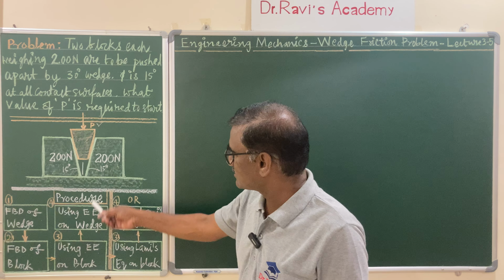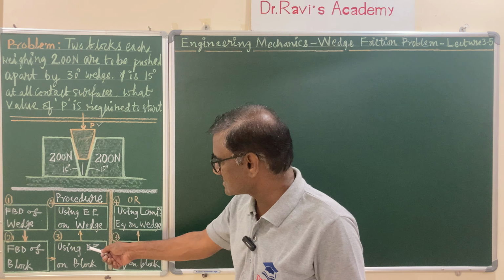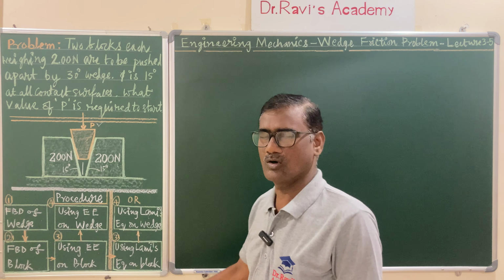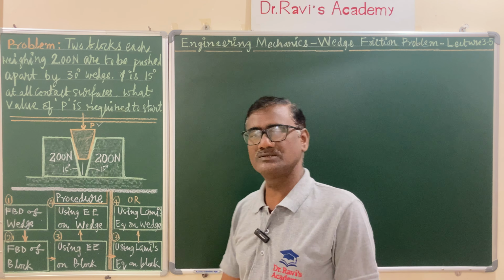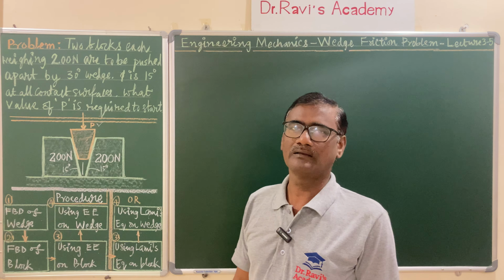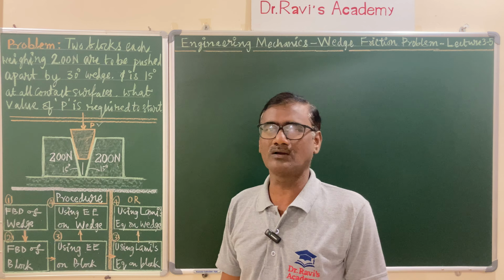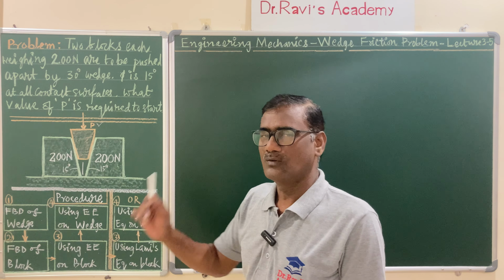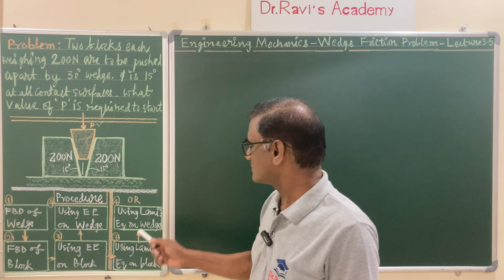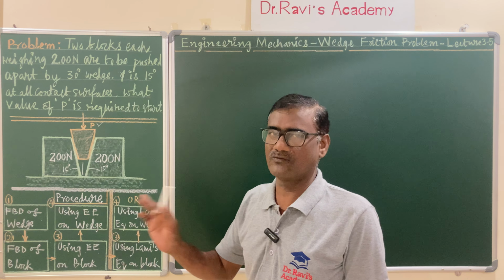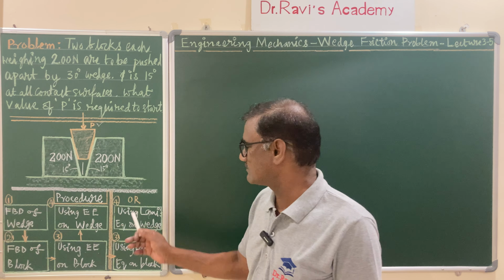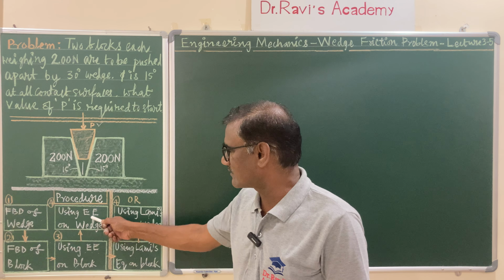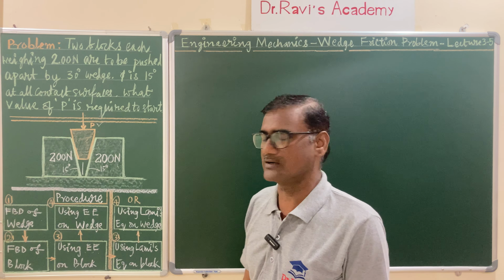This problem you can solve using equations of equilibrium, or else you can solve by Lami's theorem. Lami's theorem, as you know very well, you can apply whenever you have three concurrent forces. Remember, only when you have three forces can you make use of Lami's theorem. Otherwise, you can't apply Lami's theorem, and you have to solve by equations of equilibrium of these concurrent forces.